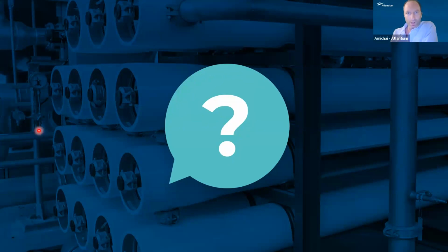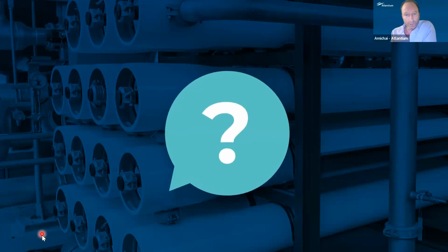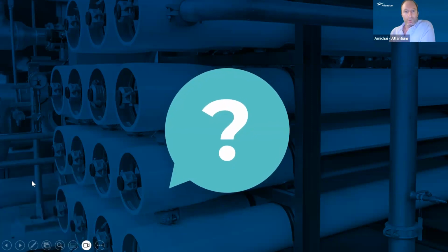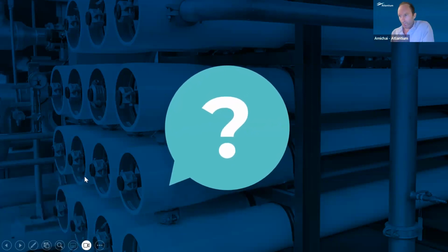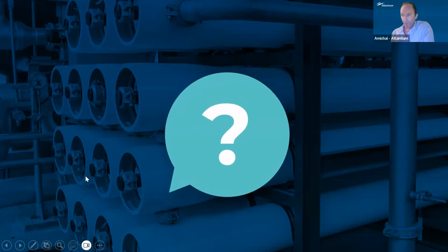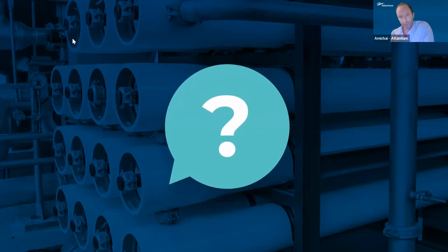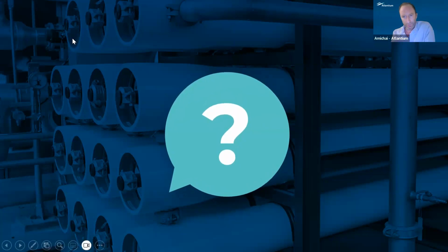With your permission, Itzik, I will take the first question because I had some notes and a rough calculation here. The first question was, what are the CapEx and OpEx differences of using UV for free chlorine removal compared to other methods, like, as we mentioned, activated carbon or chemical dechlorination? It's hard to compare, because one needs to take into account the downtime, the chemical usage, and other parameters.